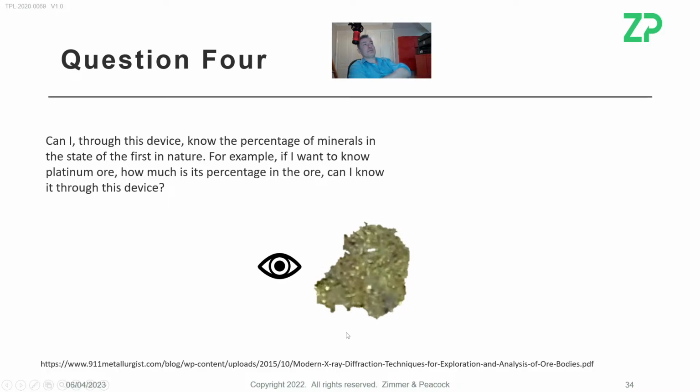I had a little think about it and thought, right, the technique is probably going to be X-ray diffraction. X-ray diffraction essentially fires X-rays at a sample. The X-rays diffract, going in different directions. The angle of that diffraction tells you about the elements, or the crystals, I should say, causing that diffraction.